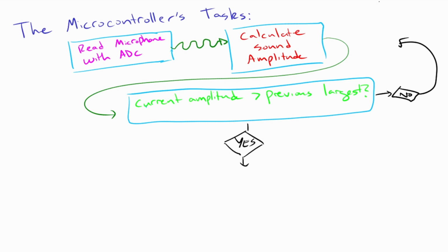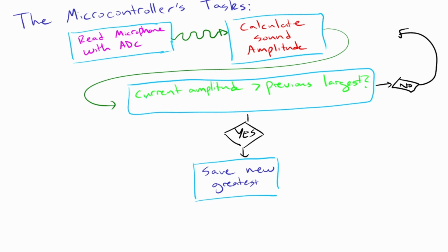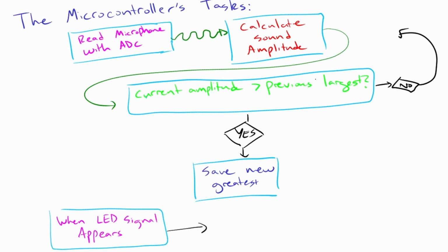The PY32 then needs to save the greatest amplitude it calculates over a given period of time. For this project, that time period is the refresh rate of the LEDs, since I only send values back when the LEDs get new data. The PY32 needs to send that value back to the main controller at the appropriate time, so that the microcontroller receives the responses in the same order that it is commanding the tiles.